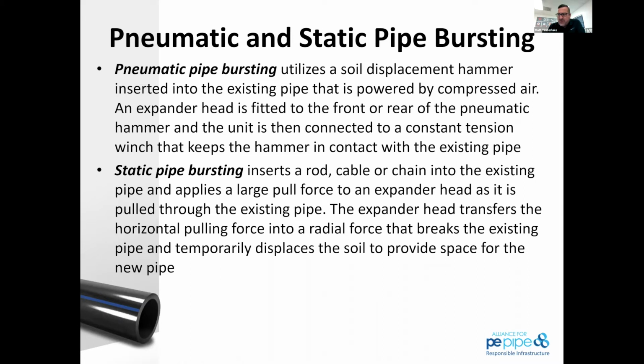The static pipe bursting method, we're accomplishing the same thing. We're just accomplishing it a little bit differently. So instead of using that pneumatic hammer, we're going to affix a head to the front of the pipe, and we're just going to pull with a static force that is going to fracture that pipe and expand the soil. So I often explain the two, that you can put a nail in a piece of wood with a hammer and pound it in, and that's the pneumatic process. Or if you push hard enough, you can actually push that nail into the piece of wood, and that would be how I'd explain the static process.